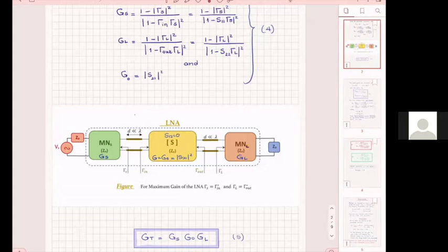For two reasons. If you try to get a transistor off the shelf and place it, this is only possible for very low frequencies. For high frequencies, let's assume you find lumped components, I don't know how high you will find those, but then you need to have holes to place them there. You need to find the ground. You need to solder it. All of this becomes very messy and does not work well.